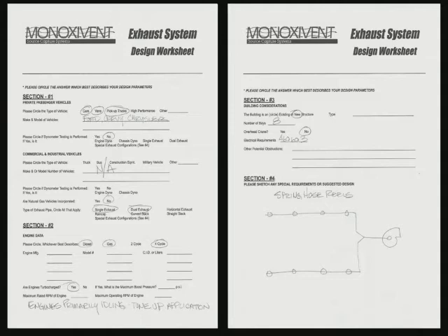There's going to be basically an open building with 4 bays on each side. We're going to have a run of duct ultimately culminating in one duct that's going to go to the fan. And what we want to do now is take these basic design parameters, the information that we've gleaned from the design worksheet, and put that on a piece of paper and design the system now, meaning size the ductwork and select some equipment to apply to this particular job.